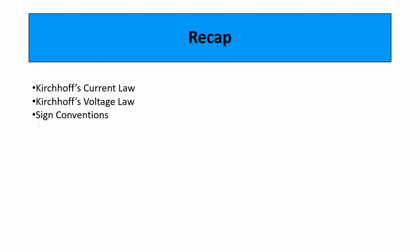When crossing a resistor, crossing in the same direction as the current means the voltage goes down. So its value is negative. When crossing a resistor in the direction opposite the current, the voltage value is positive. So it is increasing. For an EMF source from positive to negative, the voltage drops. So the value is negative. From negative to positive, the voltage goes up. So the value is positive.